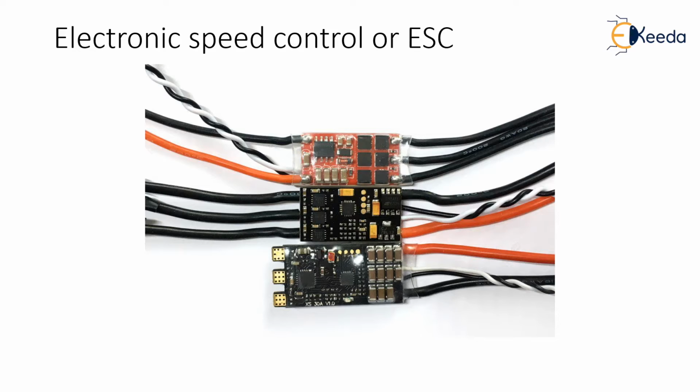The process of doing so starts with the aircraft's flight controller, which receives the pilot instructions, then translates them into digital commands which it sends to the ESC. The ESC, in turn, interprets these instructions and increases or decreases the voltage sent to individual motors.